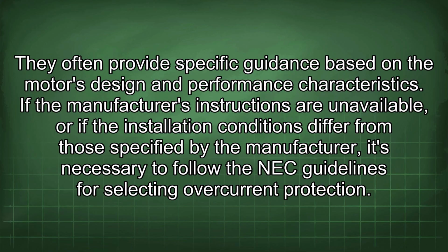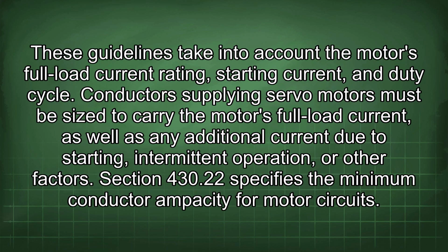If the manufacturer's instructions are unavailable, or if the installation conditions differ from those specified by the manufacturer, it's necessary to follow the NEC guidelines for selecting overcurrent protection. These guidelines take into account the motor's full load current rating, starting current, and duty cycle. Conductors supplying servo motors must be sized to carry the motor's full load current, as well as any additional current due to starting, intermittent operation, or other factors.